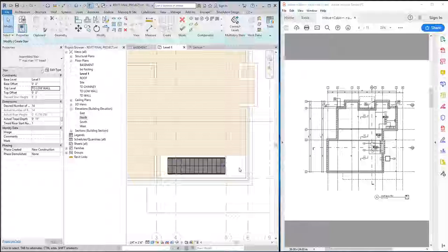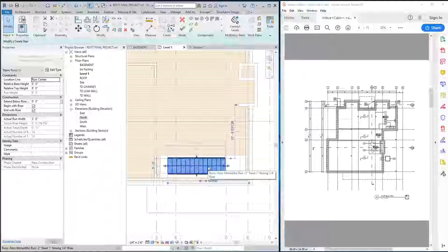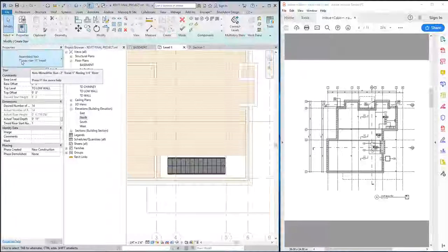It used to be that if I decided, oh, I don't want this stair to be a 7-inch maximum riser, 11-inch tread, I want it to have a 6-inch riser and a 10-inch tread, I could, after I had drawn them, make that change, and Revit would say, hey, your stairs don't comply anymore, but we're going to recalculate. And it doesn't do that anymore. So if you don't get it defined correctly the first time, I found the best way of going about changing it is just to delete it and redraw it, for me at least.